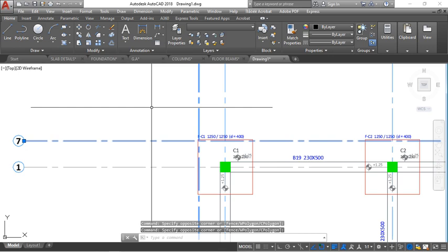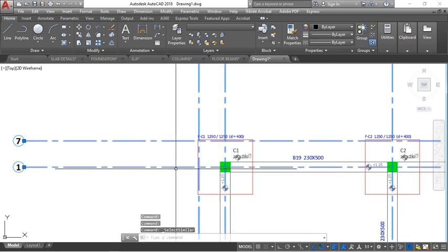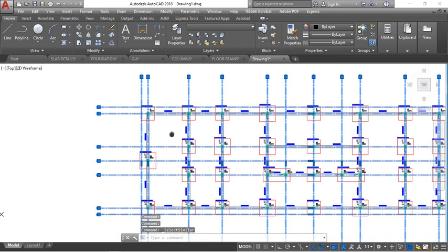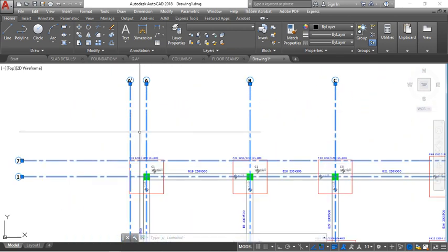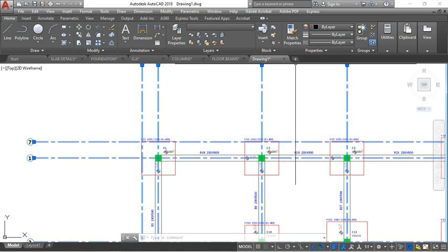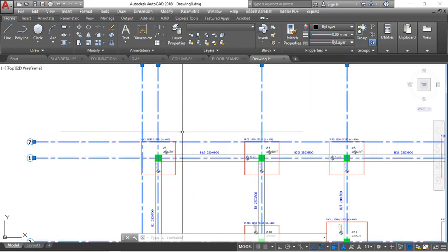When I select, because the one on the vertical is different from the one on the horizontal, you have to select the two. Then when you right click, you select similar. Once you do select similar, it will highlight everything with that particular layer. Most of it, when you click print, this might be thick. So when I want to print, I don't want this to be thick. I want the line weight to be 0. So I just click 0. The line weight is 0.